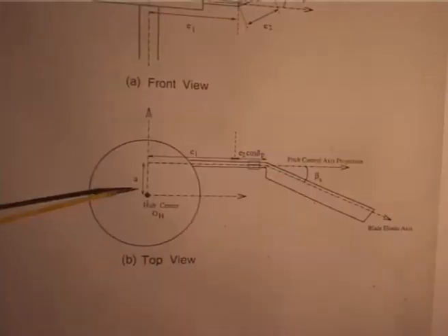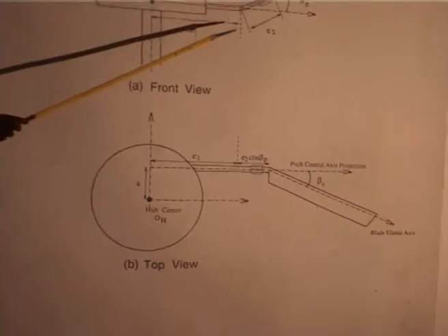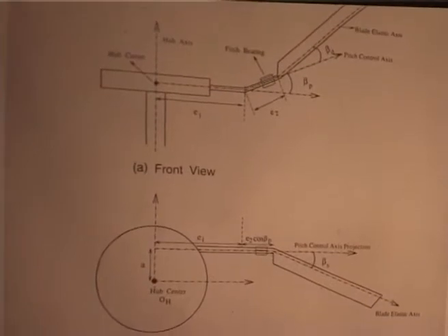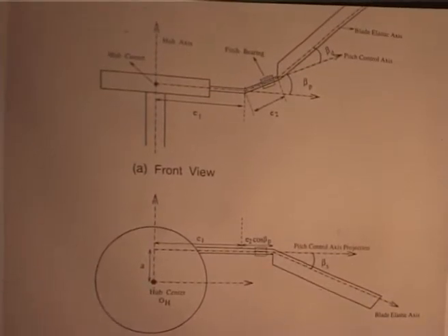Now, this is the torque offset, these are hinge offset and pre-cone, pre-flap or pre-droop and then pre-sweep. These are the geometrical complexities in a rotor hub, but it is not necessary that all the rotor blades should have everything. That depends on the experience of the manufacturer.